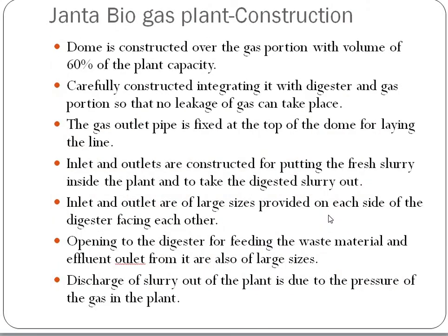Construction wise, the dome is constructed over the gas portion with a volume of 60% of plant capacity. It is carefully constructed, integrating it with the digester and gas portion, so that no leakage of gas can take place. Care must be taken that the digester and gas portion are properly sealed. The gas outlet pipe is fixed at the top of the dome for laying the line.